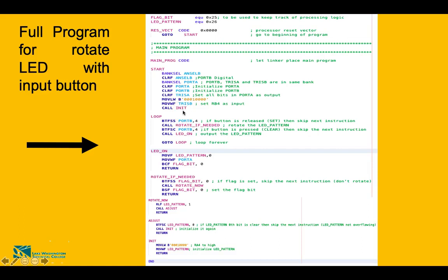Now you must be looking at the INIT code. It's actually at the bottom. It doesn't matter wherever you place it. It's a subroutine. You can call this subroutine anywhere. It doesn't have to be in order. So your program just looks for this INIT in your code. So it sees here, and what does it say? It says transfer this literal number first to the working register, and from the working register to this general purpose register, and then return. And then go to the loop.